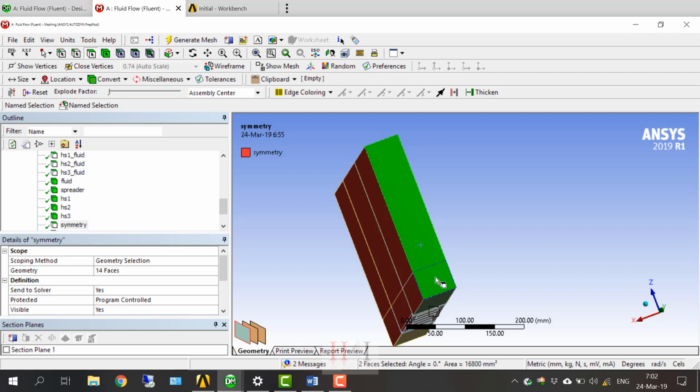I'm sucking it to me, so I'm not the source of energy. It comes from its own energy. So it sacrifices part of its energy by decreasing its static pressure, converting it to dynamic pressure. So we find that static pressure is lower than the ambient pressure when the flow is coming to me. The total pressure is equal to the ambient pressure because it is coming from the ambient. All of this is done by defining the boundary as a pressure outlet.